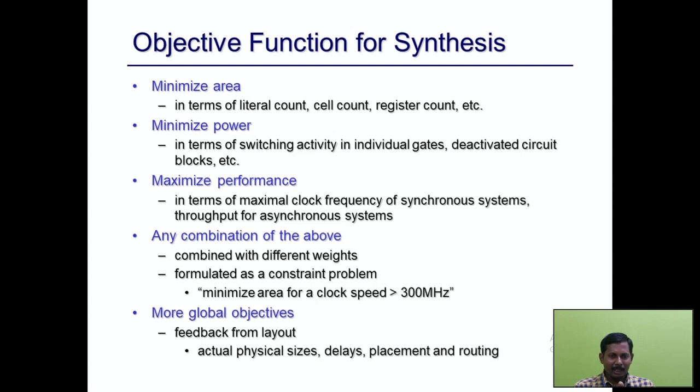If the timing analysis fails, definitely we can't maximize the frequency further. So we need to step down the frequency and again validate the timing analysis. Once the timing analysis is perfect, we fix that frequency as the maximum operating frequency of the processor.